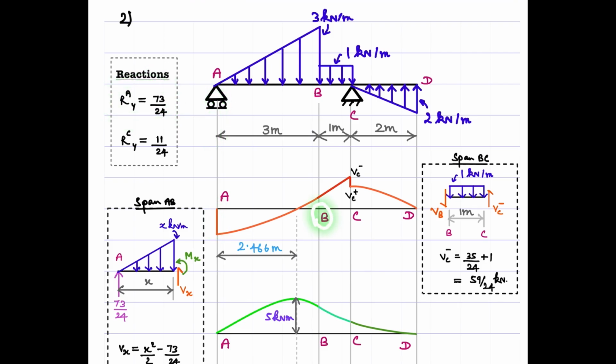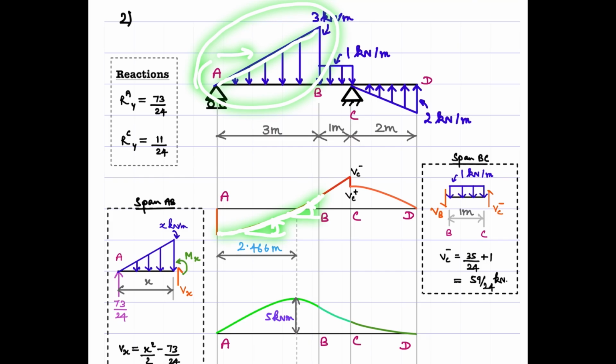Now when you reach point B, you should also know what is the value of the shear force at this joint B. Okay. Only then you can say whether it is going, I mean, one needs to determine what is the height also. Okay. So in order to do that, one starts with this value and sees that you have this negative one which is gradually increasing from the left hand. Therefore, this pattern should be like this. Only then you can relate this positive slope which is gradually increasing from the left hand towards the right hand to the corresponding negative ordinates here. Okay, so that's the way we determine this variation here.